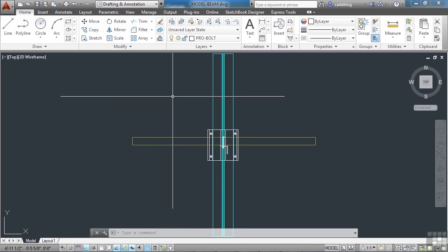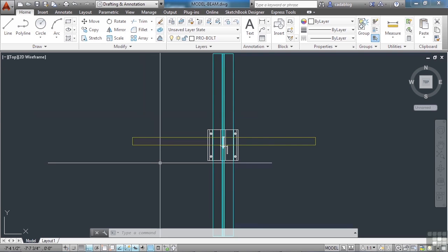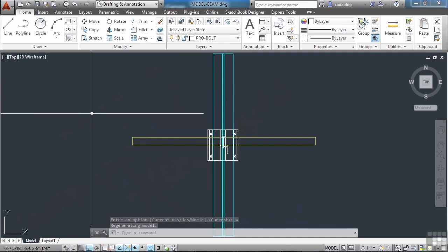When we draw in 2D in AutoCAD, we typically are drawing in just the top view. That puts us at an elevation of 0. So you have your X, you have your Y, and then your Z factor or your Z axis, as you can see, is right here, vertically up and down. That usually stays at 0. Now the 3D orbit is fun. It's quick and very easy to do, but it lacks precision. And you can use it in model space. You can even use it in a viewport in paper space. But if you want to rotate your view precisely, you're going to want to use the dview command.